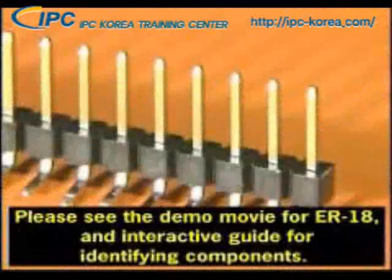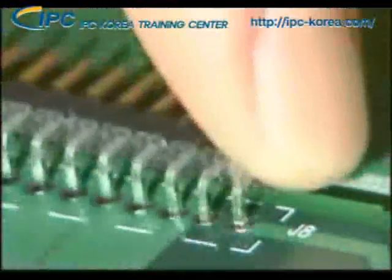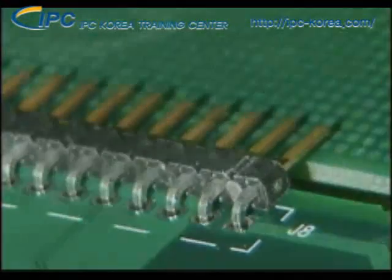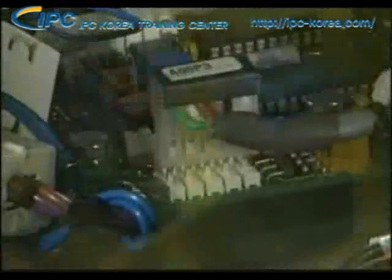The next type of connecting hardware we'll discuss is the header. Like connectors, they are used for outside connections. Headers usually don't have a housing around their pins. They also use the letter J or P as a reference designator. Headers usually have alignment or locking tabs for the connector which mates with it.